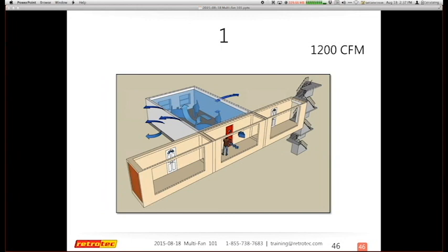So I do a blower door test, and I get 1200 CFM on this first unit. And now I want to find out what is the real leakage to either the unit, so I can focus on those repairs, or to find out what is actually the leakage of this unit itself. This is a challenge in terms of code. If I want to do a blower door, do I include neighboring units, or am I able to neutralize or subtract neighboring units?